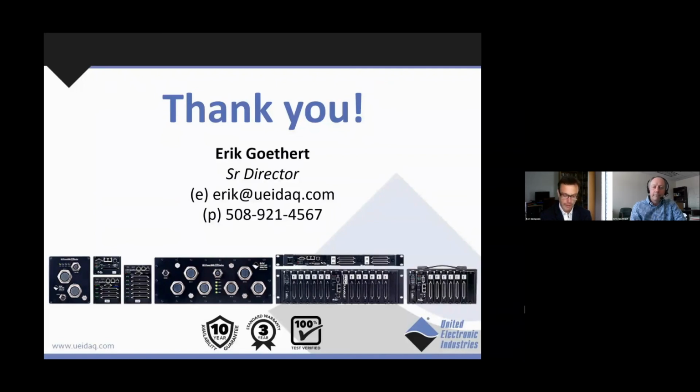Okay, fantastic. And you're an embedded systems guy. Do you have a fully standalone embedded controller that's available for this stuff? Yes, our hardware runs in two modes, and one is a standalone, fully embedded mode running a real-time Linux or VxWorks. And the same application can run on the hardware when it's in our distributed networking mode. And the distributed networking mode relies on the application running on a PC.